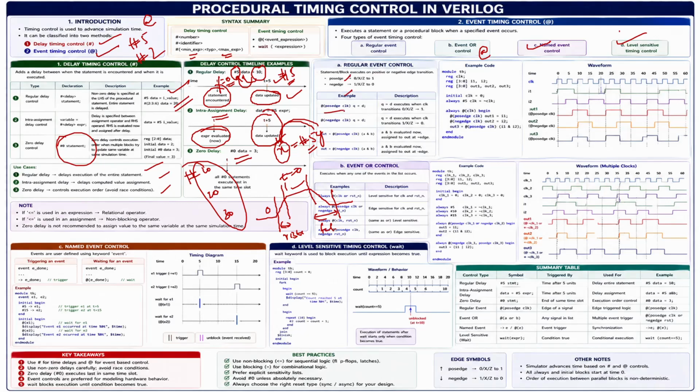That means always at posedge clock you will be assigned, so then your design output will appear at the posedge clock. Sometimes we can take the negedge clock, and sometimes we take the asynchronous reset condition also. Combinational circuits can also be executed on posedge clock and negedge clock. This is all our regular events. Based on that clock only it is executing.